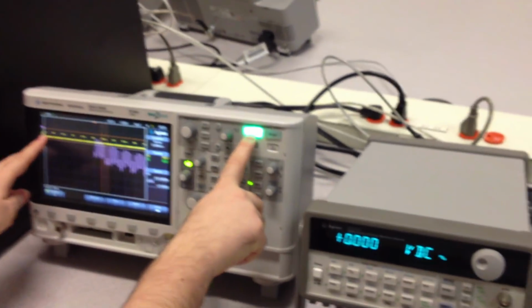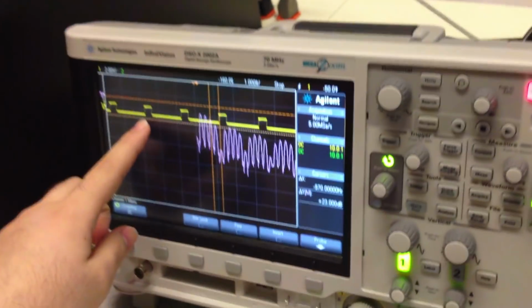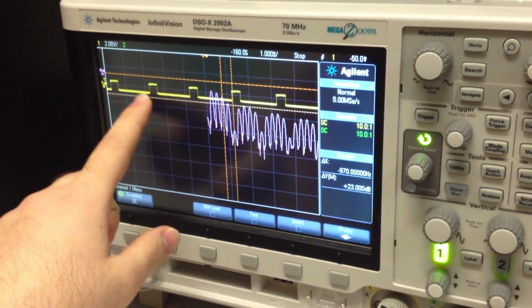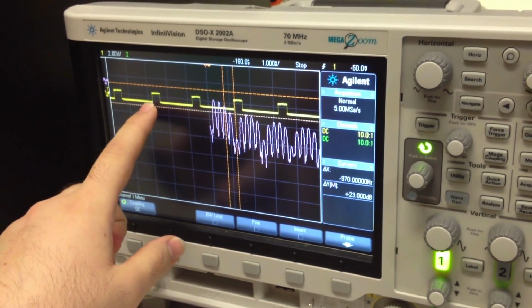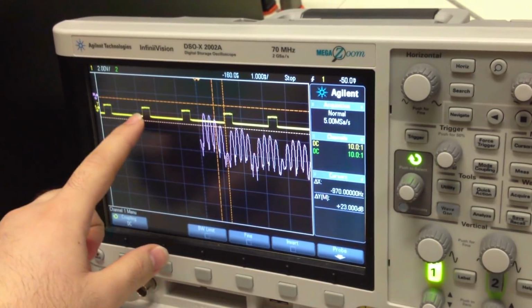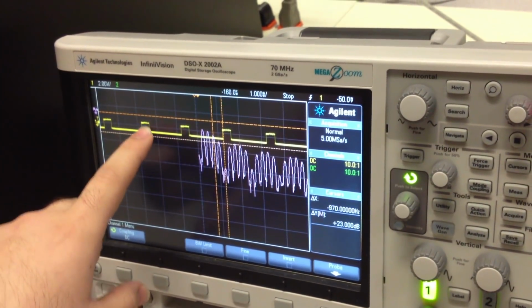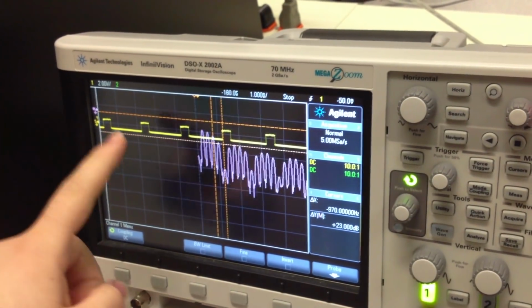Let's see it in the scope. Let's stop the wave. That's it. You know that's the duty cycle of 20%. It is up for 20%, then down for 80%. With the peak, the scale is 2 volt, so this is nearly half the scale. That's 1 volt. This is 1 volt.